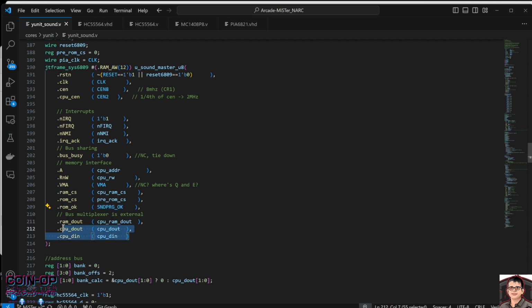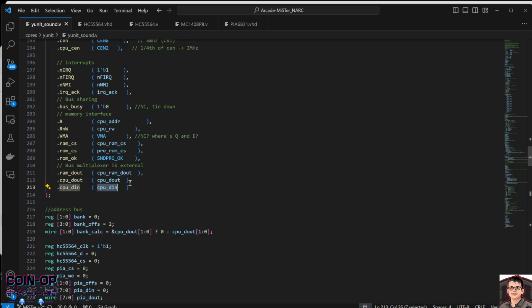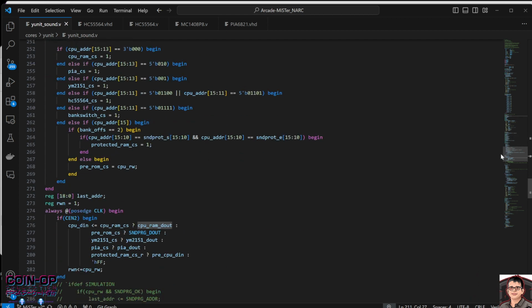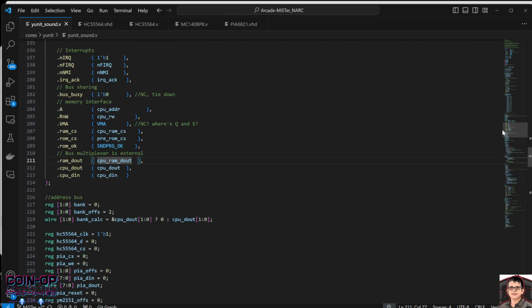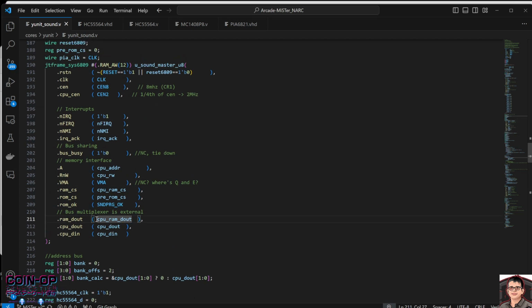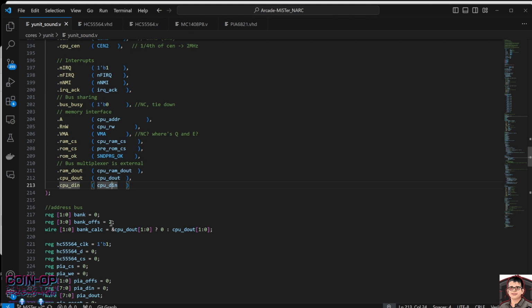The next series of pins are basically data pins. So this is the D out from the RAM. This is out from the CPU. This is into the CPU. Okay, and that's pretty straightforward. So since this is managing the RAM, right? You have a case where this wrapper is actually going to output whatever is in the RAM contents of whatever the address is here, right? But then you have to feed that potentially back into the CPU on a different port, if that makes sense. But yeah, I'll show you that down in this file.